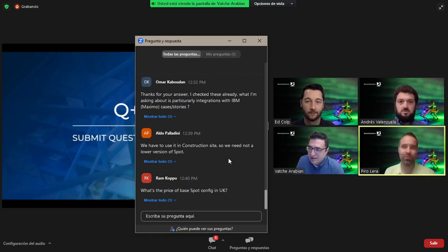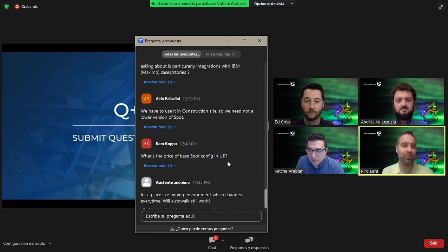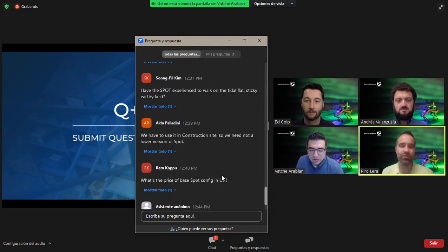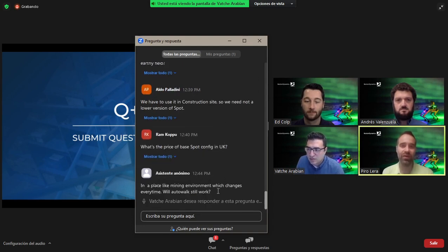I can start with that, yeah. So the idea is, docking is the first step, because the docks all have the fiducials that are part of the initialization as well. On top of that, there are the maps as well as the no-go map views provided as part of the navigation system. So it's related to having the maps as well as the fiducials in place, and as part of the mission playback, that would allow the robot to navigate autonomously, localize itself, and be able to replay the missions in that environment.